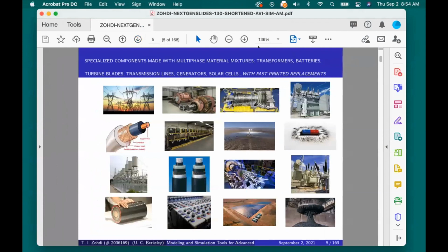Our primary interest, as we said a little bit earlier, was in the additive manufacturing of large-scale machine parts. It was primarily driven by energy analyses, so essentially designing thermoelectric cables, generator components, turbines, things of that sort, and using additive manufacturing and advanced manufacturing in general to design very specialized parts. The specialized parts, in this case, could be a composite thermomechanical component, such as a turbine blade. Many are now being fielded that go beyond simply titanium and super nickel alloys, but now have some combination of ceramic and metallics.